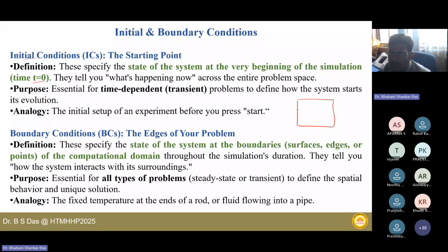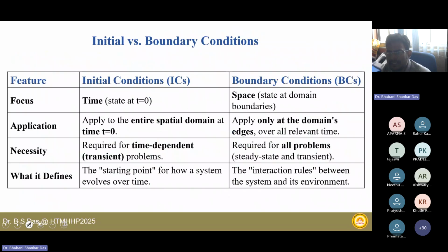When there is no dam break, how is the scenario, how are the cells, what is the velocity value in each cell, what is the depth of flow, that is the time 0 value. In a time dependent problem, you have to give the initial condition at the beginning of the simulation. Otherwise, the simulation will not occur. In 1D flow, in HEC-RAS also, you are giving some initial condition and boundary condition. Otherwise, you cannot initiate the problem if you are not defining the domain. You will not get the results at each node. So these are some differences between initial condition and boundary condition.